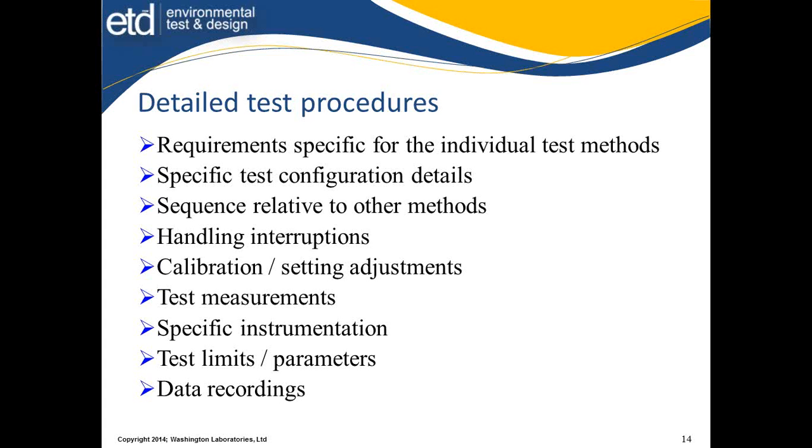How am I going to collect measurement data? A lot of folks write procedures that still use handwritten data. Our technology is getting away from that rapidly. Allow for spreadsheets to reduce data where you plug in a number and the math is accomplished. I personally prefer these methods because once you validate your equations, you don't have math errors that creep in. All you've got is keyboard entry errors. Do I need to print it and get a signature? Or can we do signatures by some other method, electronic signatures and approvals? You need to figure out what's going to be dealt with in your procedure.